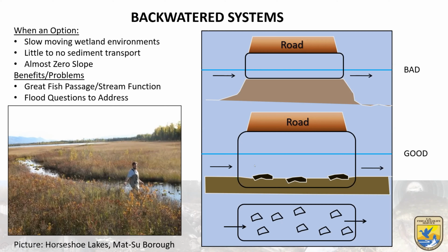And so we put these things and bed them down below the natural depth of the creek. At times we've even just put pea gravel in these things, but we always make sure to put a good amount of larger cobbles in them, again, to help with predation potential issues.